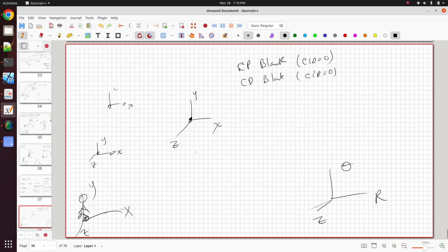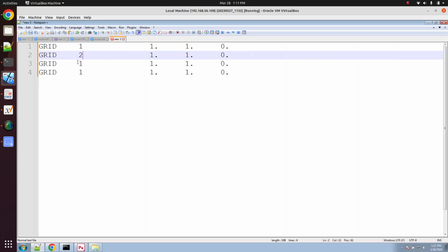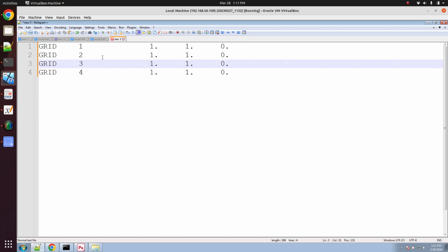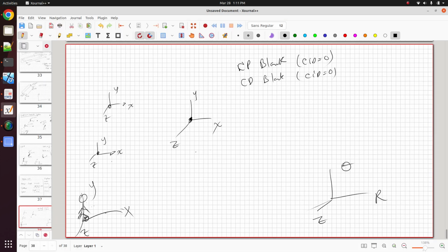So here if I draw multiple points, all of these points, as long as you use blanks for all of them, are going to share displacement coordinate systems with parallel axes, if you will. So let me give you an example. So here, 2, 3, and 4. Here I've defined various points. All of these points are going to have these displacement coordinate systems, if you will. But if I switch to the cylindrical coordinate system, that's when you're going to have a lot of fun. So here, let me quickly draw what those look like.